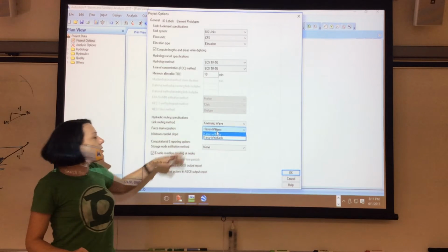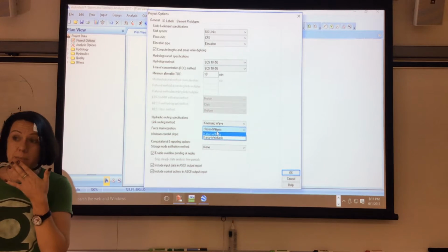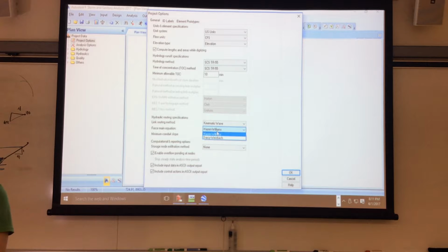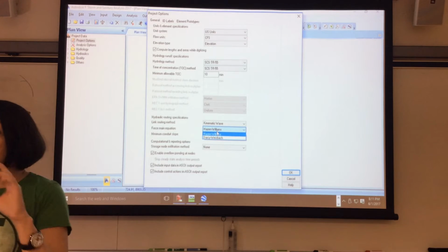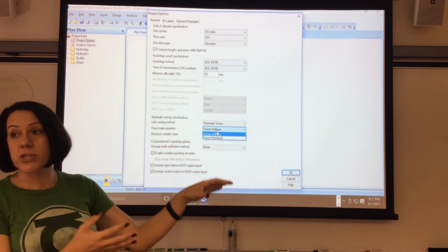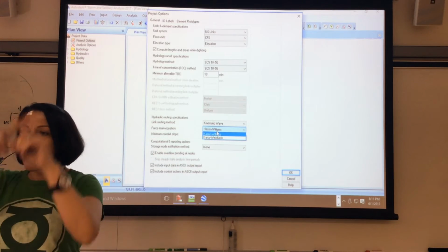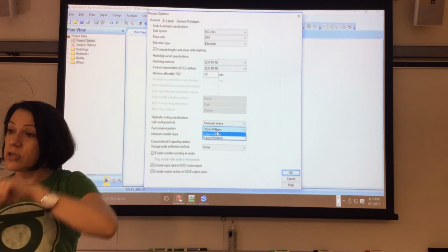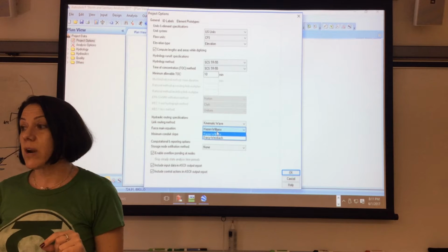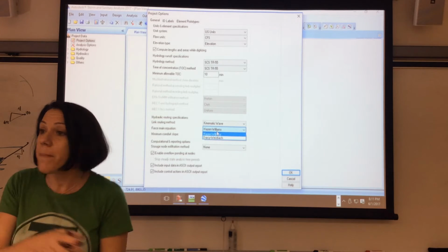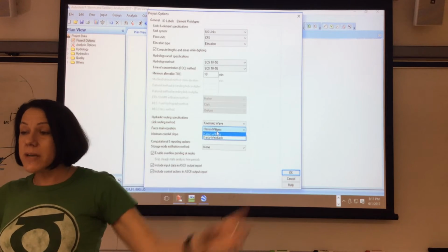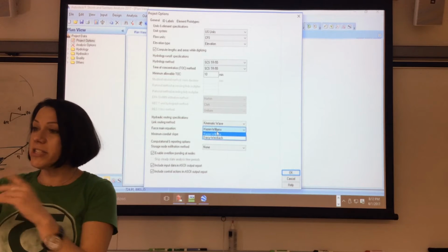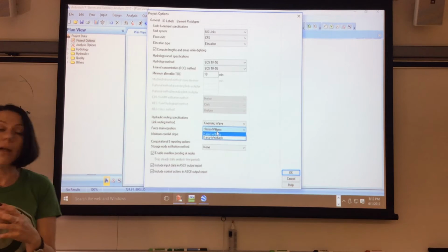Anyway, it's similar to that. When you're working with a force main, it's all under pressure. So when you're under pressure, water can go any direction. It's not gravity fed. It's whatever has the higher pressure head that's forcing the water in the direction it's going. So imagine you have a grid system. Wherever the higher pressure is controlling, it's sending water in a different direction. So if you turn on your tap, it's going to pull water. So now it's looking at all the different places that have a pull on the system.